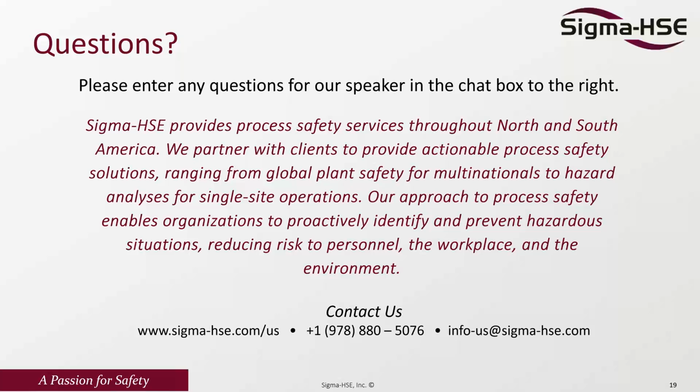All right, thank you. Another one here is why is it important to document management of change and incident investigations? That's a good question. First of all, the management of change is a review of any changes to ensure that the basis of safety study recommendations are not being violated. So part of the reason for the management of change is to ensure that the basis of safety of your unit operation is maintained.